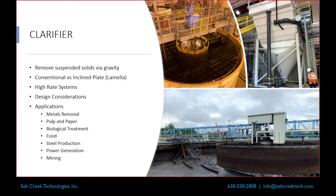Yeah. So I think it depends really on the design of the lamella you have. This style here, where it's got a large hopper on the bottom, I'm fine keeping a fairly good size sludge blanket in the bottom. A lot of systems, this one doesn't, will actually have an auger there to help, because while it's sitting there it's also compacting, so it's dewatering and thickening more. Some of them have an auger or some sort of device rotating in the bottom to allow water to get freed out of that sludge and come back out. So you get a thicker sludge if you leave it in there.